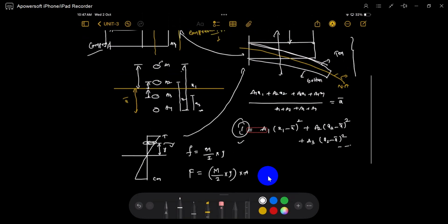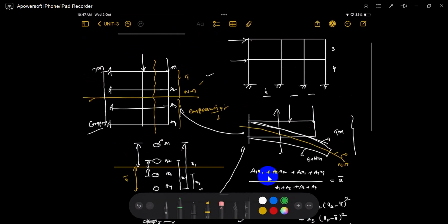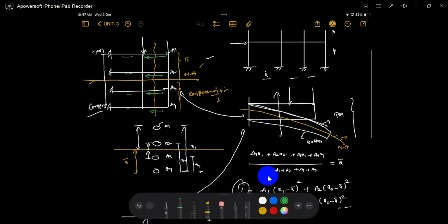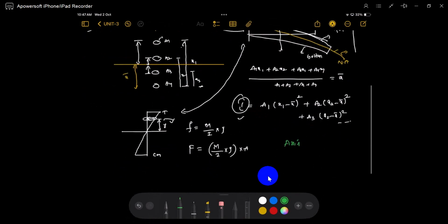You already know this from simple bending theory of any section, so consider the same here. Consider the axial force, not stress, in each zone. So first we calculate the axial force in the columns based on cantilever theory, that is, simple bending theory.